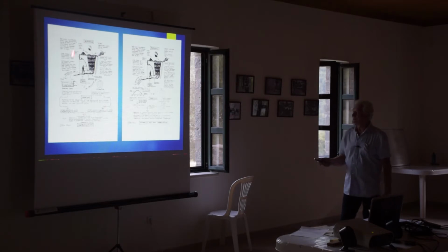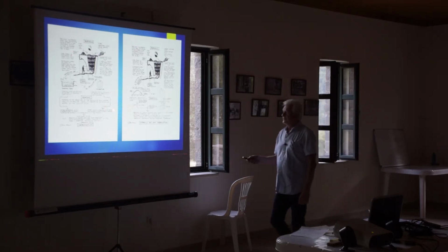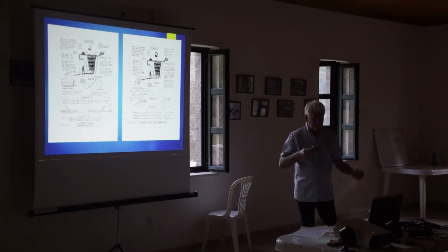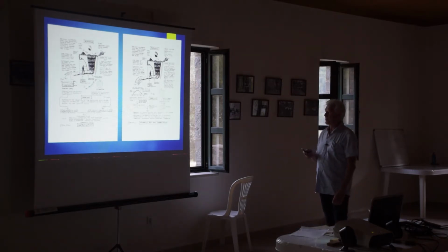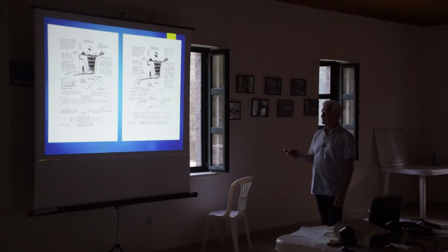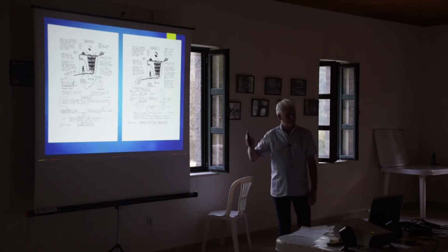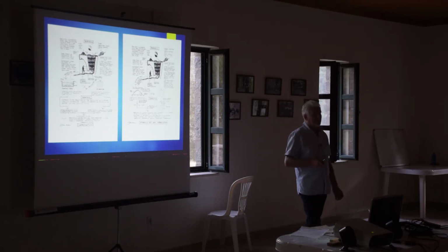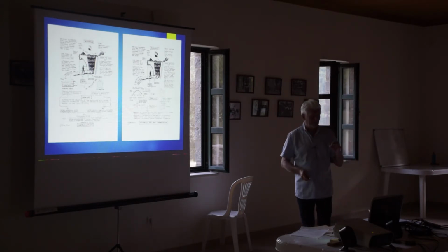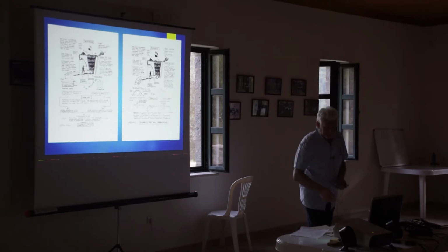This is basically how it happens with a kiln. You fire the kiln from the bottom. The limestone is fed in from the top. You get layers of timber, layers of stone, layers of timber, layers of stone, all the way up through. I'll show you some actual slides in a minute. And through this burning process, we change from the original material through to the quicklime. And when it comes out of the kiln at this point, that's the quicklime. These are little blocks which you're going to see.